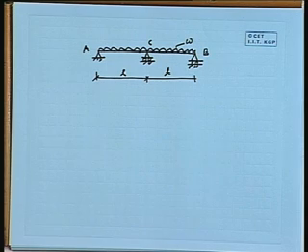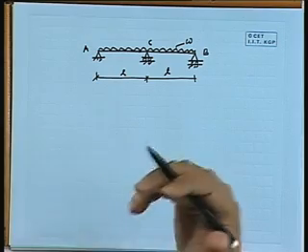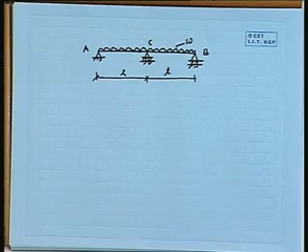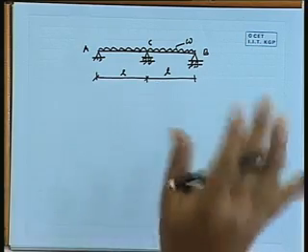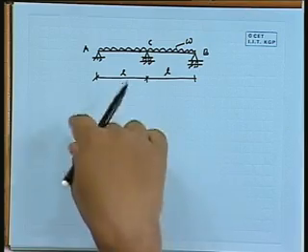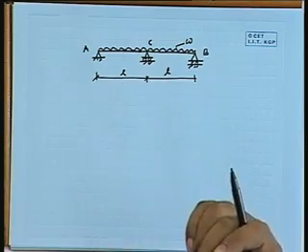Now, already that problem was defining, because there are 3 vertical reactions plus 1 horizontal reaction, though that will be 0, but we have to take it. So, 4 is the total number of unknowns, and 3 equations of statics. So, the extra equations we require equal the extra number of unknowns.